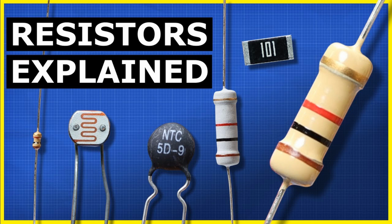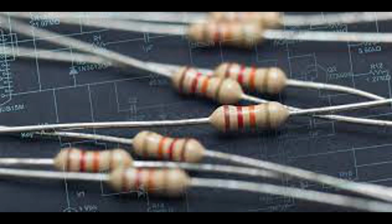Effective temperature: noise in resistors increases with temperature. As the temperature of a resistor rises, the thermal motion of charge carriers becomes more pronounced, leading to higher levels of noise. To reduce noise, low-temperature coefficient resistors, those with a low temperature coefficient of resistance, or TCR, are often used. Low-noise resistors: for applications where noise is a critical concern, such as in precision amplifiers or low-noise audio circuits, specialized low-noise resistors are used. These resistors are designed to have lower inherent noise levels compared to standard resistors.